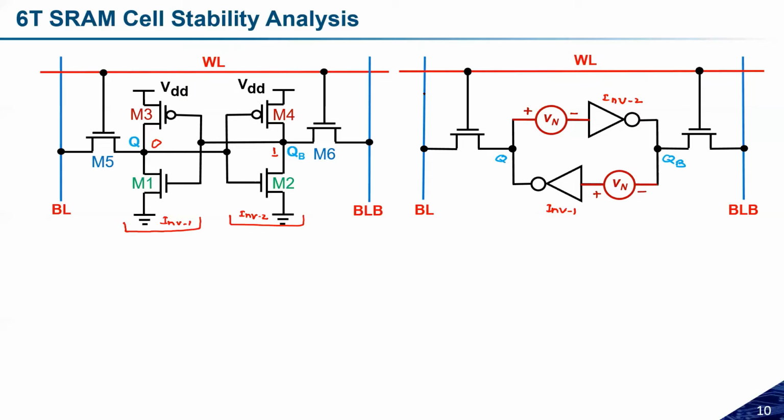As we have shown in the second figure, the noise sources are included with the worst polarity, and this has been given. As the voltage is applied, the voltage transfer characteristics of this inverter change. Suppose the Vn is increasing, then the voltage transfer characteristics will move somewhere here and there.